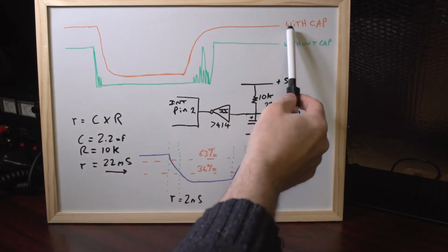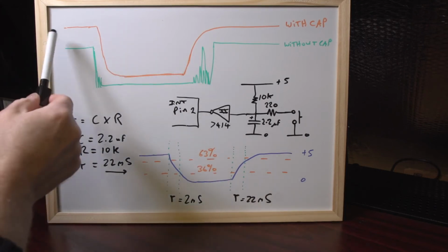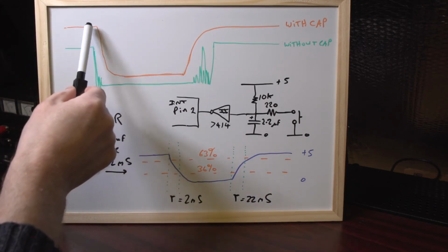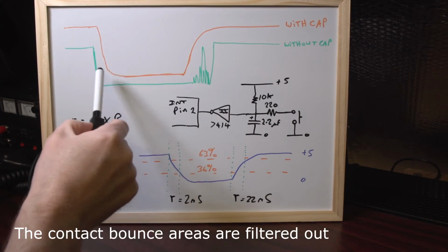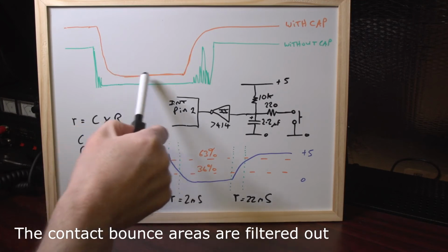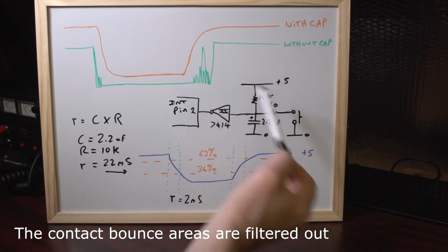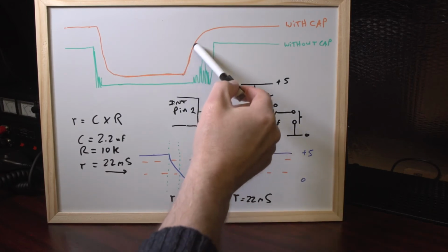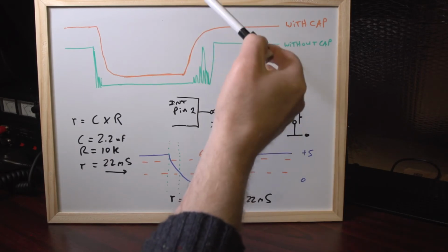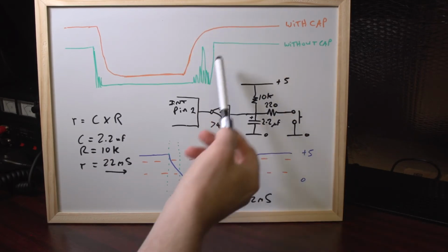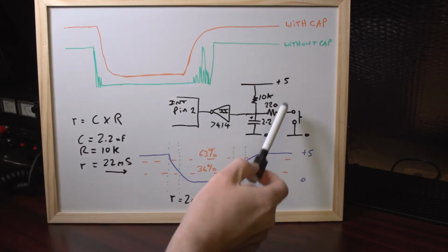Now if you look at the orange graph, basically that's all I've said. High level, then you push the button, then you get a nice capacitor discharge curve within a very short period of time, probably a millisecond, and then down to a low level, or pretty close to low. And then when you release the button, you get a nice big 22 millisecond release time here, going back up to high. A typical capacitor charge curve there. So you'll notice there are no more spikes here, and no more spikes here either. All that's gone, and that's our time constant.